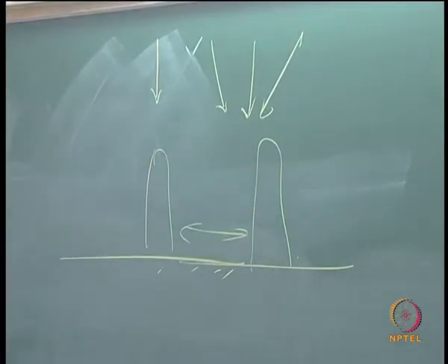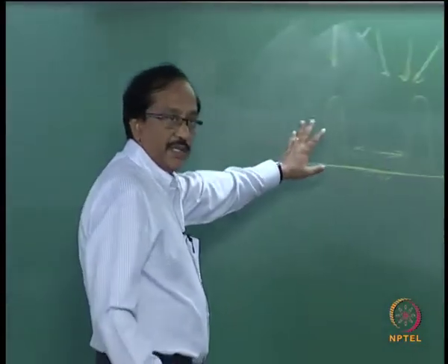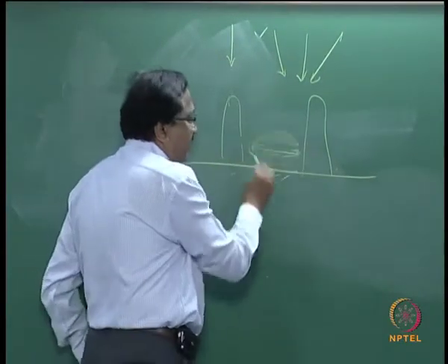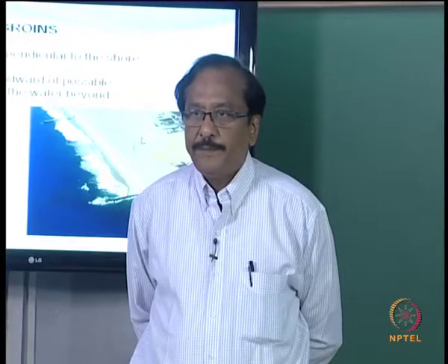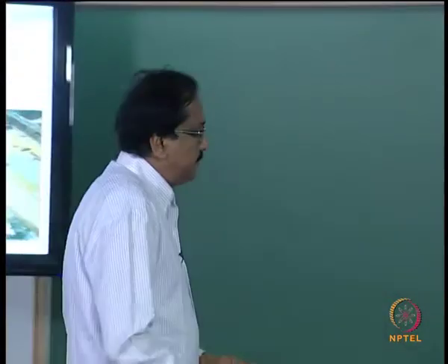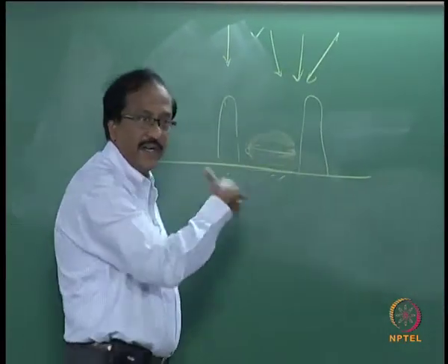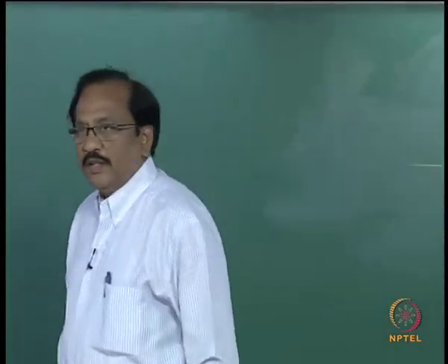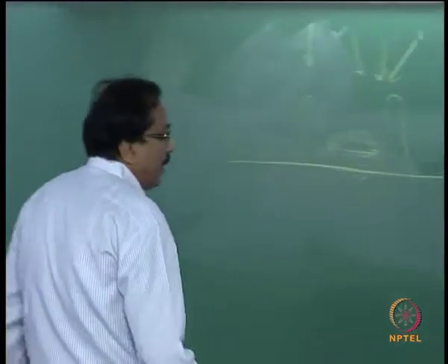When you have cross reflection, and that too with impermeable groins, there will be a lot of oscillations, or magnifying of the wave heights. So, it is important to have this dissipated in the lateral direction also. That is why it is always better to have permeability involved.